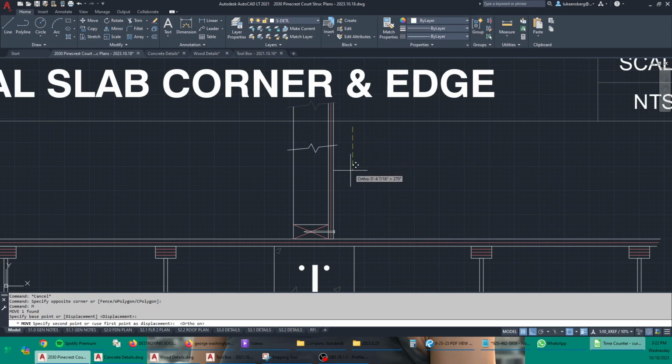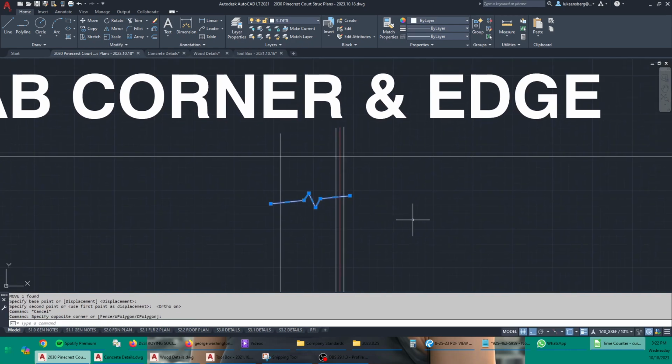Bring that down a little bit using the move command. Highlight this to make it a trimming edge and then TR for trim. Boom, gone.